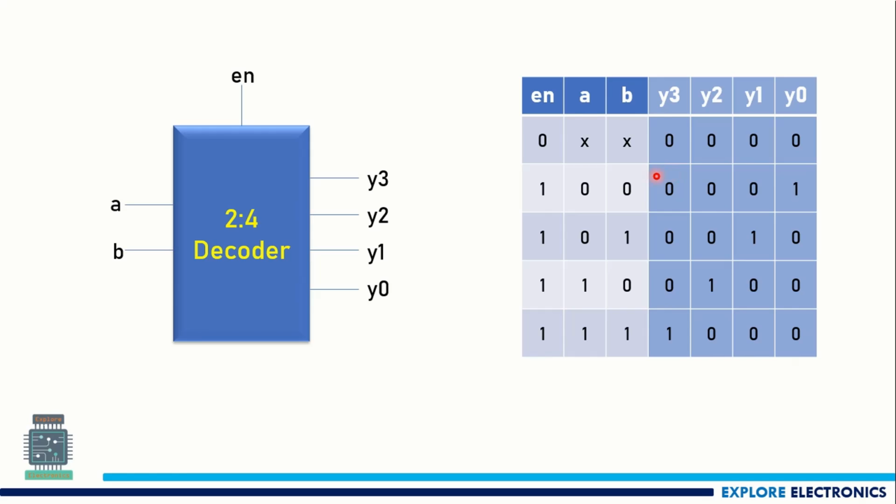You may sometimes have a different decoded output. Depending on the necessity of the decoder, this decoding output will be decided. For 0, 0, it might be 1, 1, 1, 0 or 1, 1, 0, 0, like that. So here the 2-bit input will be decoded to a 4-bit value. That is what we need to understand.